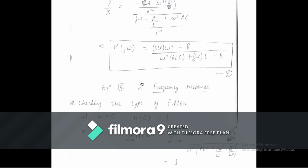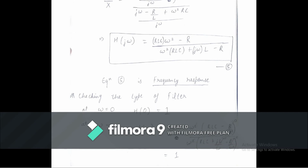Now we will check the type of filter from our frequency response. First we check at omega equal to 0, and we get H of 0 as 1. When omega tends to infinity, we take the limiting value and we get that value also equal to 1. So we can see that our numerator will get to 0 somewhere in between.